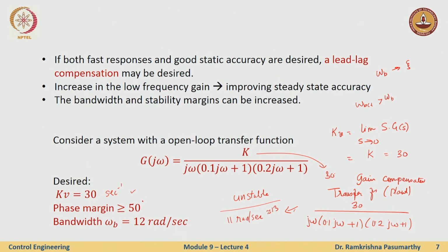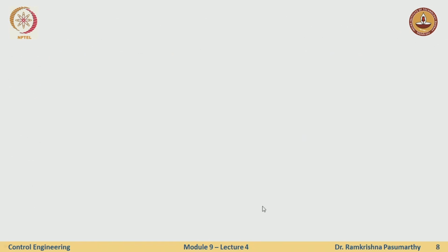So this we may have to check. You may take the Bode plot for the closed loop system and see that the bandwidth for the closed loop system is actually 13 radians per second. However, this is not very useful to us because I am just dealing with an unstable system. Now let's just try what happens with just using a compensator. I'll just write down the steps here. Let me just take arbitrarily any.